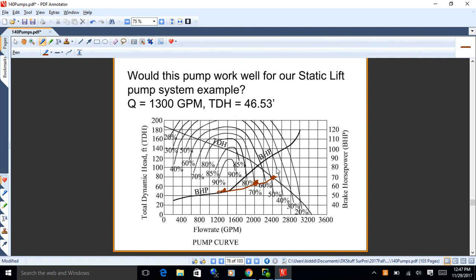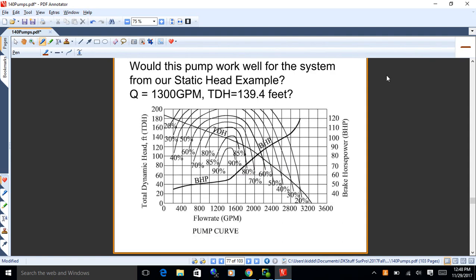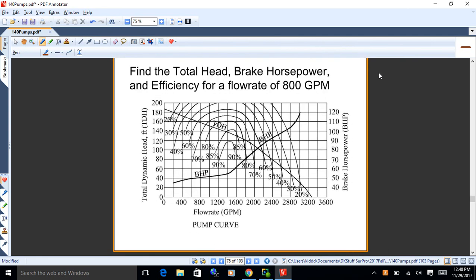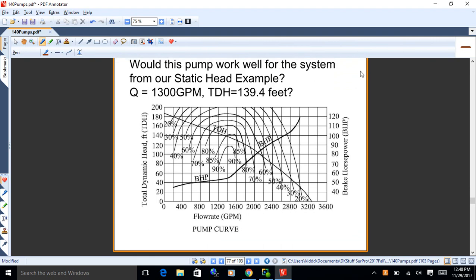And then when it hits the pump curve, of course, it stops. Now, is this a good place for the pump to be running? No, efficiency is horrible, okay? So you don't want to use this pump to do this job. It's too overpowered. It doesn't run efficiently at this rate. It's going too hard. It prefers more resistance. And what it prefers to do is this situation right there.